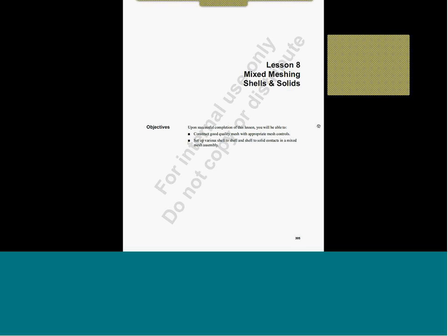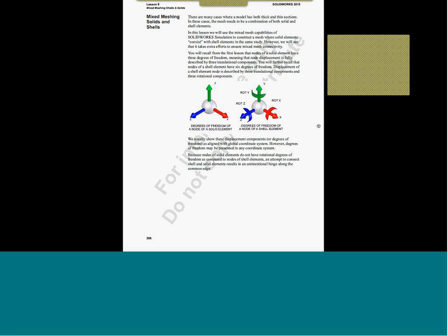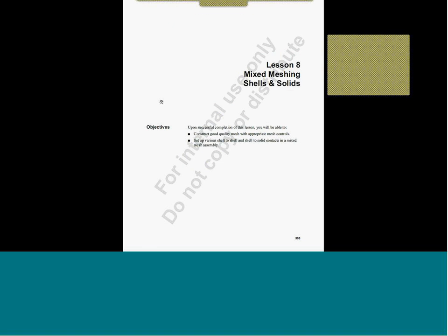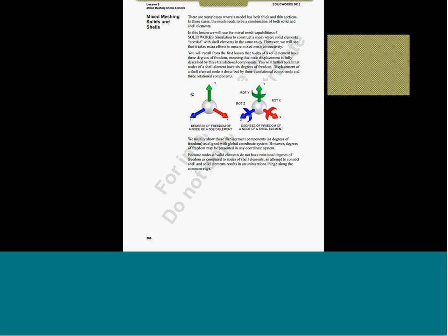Okay, now most of us are comfortable with the concept that in the case of solid elements, at a certain node, we will have only 3 degrees of freedom. So you see here, it has only 3 degrees of freedom at a given node, whereas when it comes to beam or shell elements, they actually have 6 degrees of freedom.